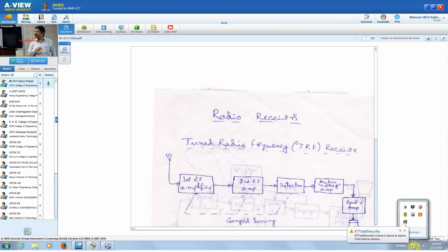So the main disadvantage is that the gain we are providing at the first stages is going to cause a feedback at the input. Therefore, this becomes an unstable system, and without any input, we are getting the output. So oscillation starts, which is not required, whereas you have to use this receiver to detect the received signal.